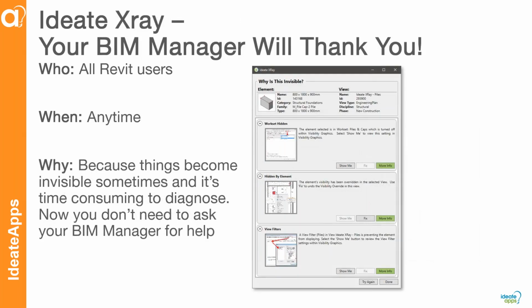And then finally on this first series of tools is our Ideate X-Ray. And X-Ray is a great asset to any organization. It allows you to understand why an element in Revit is not visible. So you may place something and you get a warning and it says, hey, I can't see this. Why? Well, is the work set hidden? Is it hidden by element? Is it a view filter? Is it outside the view range? We've actually come up with over 50 different ways an element can be hidden within Revit. And so Ideate X-Ray is going to help you understand why that element is not displaying.